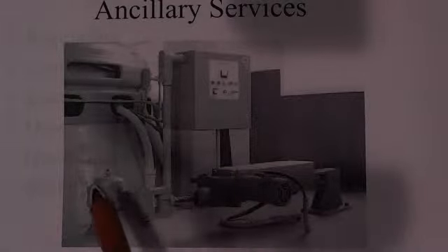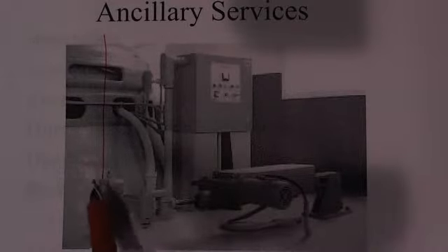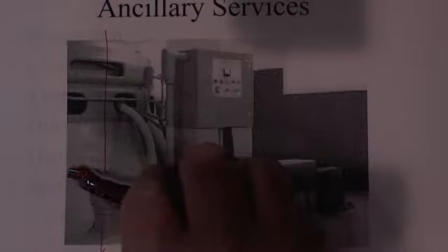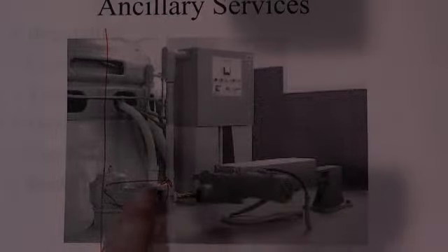But it turns out that there's a lot more to operating a power system than energy. And what we see here, I love this little picture, is the shaft of a hydro system valve, and we want to regulate the generator, and so we have this device here, which has got a motor and a piston in it. It's going to swing this thing back and forth like this, and that regulates the hydro valve, and that hydro valve then controls how much water. So this thing is adjusting the valve,